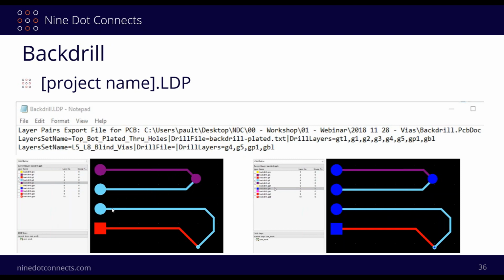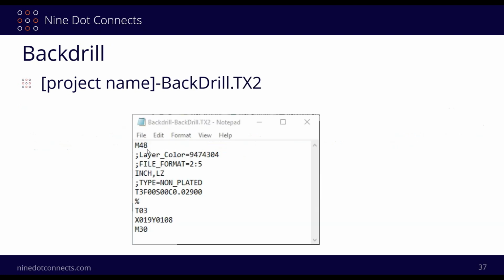And that's what you're kind of seeing over here when I took the Camtastic shot. So we started on layer 1 here. You can see this went from layer 5. And I think I did another layer over here just to kind of show this. But here's the bottom layer. And the point I wanted to make over here is that you don't see the bottom layer here really for this through hole. It's a little tiny hole, but that's all it recognizes. I don't even know why they put copper on that, to be perfectly honest with you, because it's going to get completely bored out anyway.